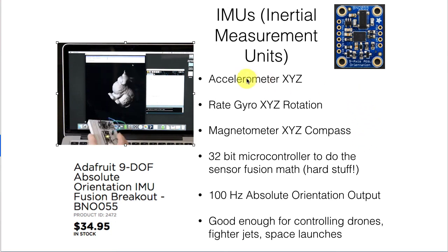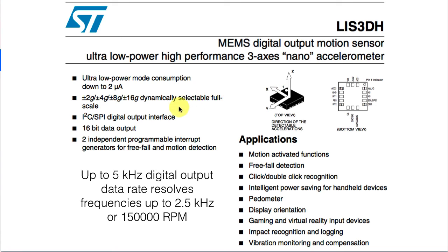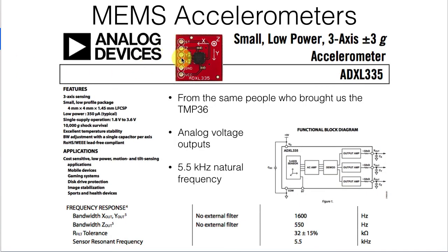So this week we'll be looking at making some accelerometer measurements with this ADXL335, an analog accelerometer. It provides us with the same kinds of capabilities that we can get from this more flexible digital accelerometer, with the simplicity of being able to interface to an analog output. We'll be measuring particularly on the x-axis and looking at accelerations, motions in the x direction, and trying to measure the acceleration, and from that integrate to get position and velocity.